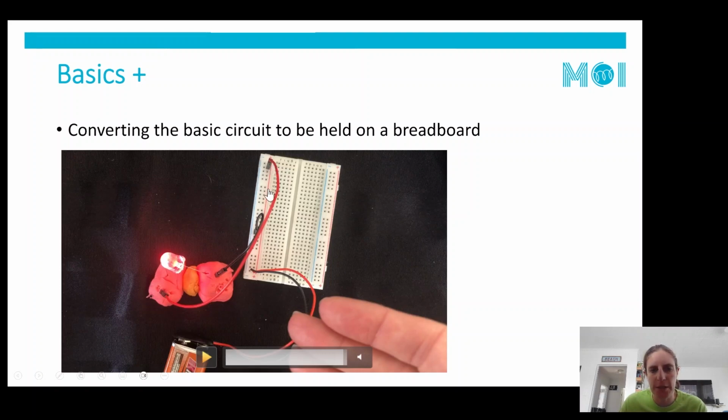You can put this plug anywhere along here, and the same our negative one anywhere along here. So if you wanted to have the stars for Matariki, you could have another positive one, and another positive one, and another positive one, etc., and have this set up 7 times. All fine. So that's how we use a breadboard to hold and connect to our circuit.